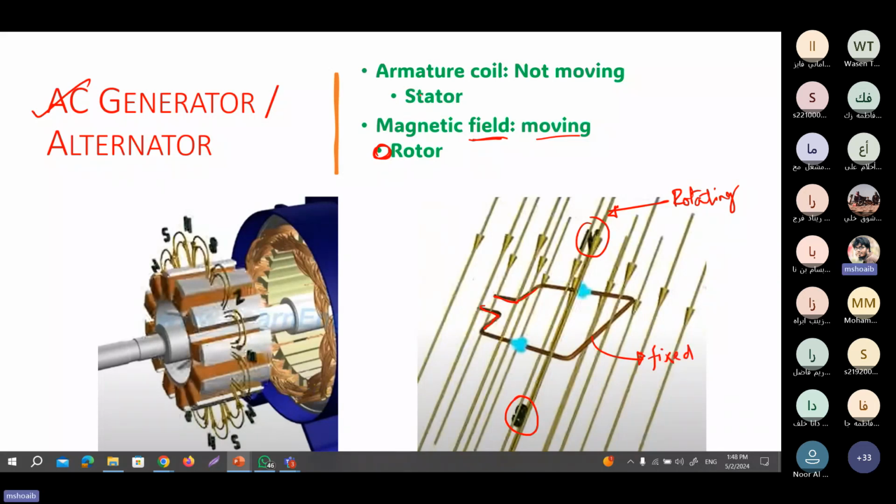So here the conductor is connected with the stator. You can look at this picture also. You see this North Pole and South Pole, and North Pole and South Pole. This magnetic field is rotating, and the coil containing the armature conductor is not rotating. But still it will generate electrical energy, isn't it? Because there is still a relative motion.